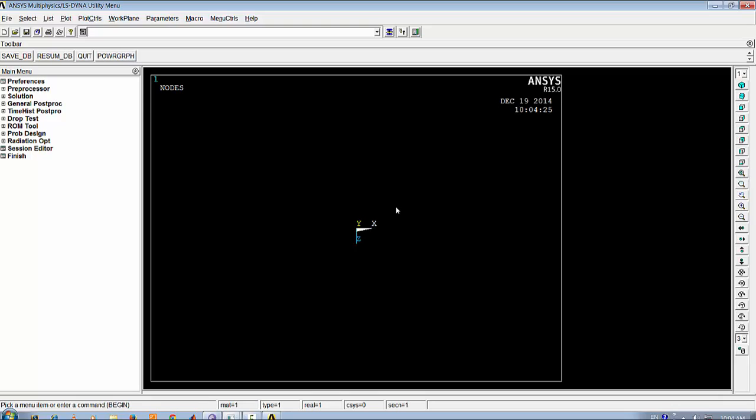And if we are zoomed out of the screen, for example, one more thing I want to add is there's an easy keyboard plus mouse combination for panning and zooming. If you have a middle mouse button, if you scroll it, you can zoom in and zoom out. If you keep the control key pressed and press the left mouse button and move it, it is panning left, right and top down. If you want to rotate it, you can just press the control key and the right mouse button and rotate.